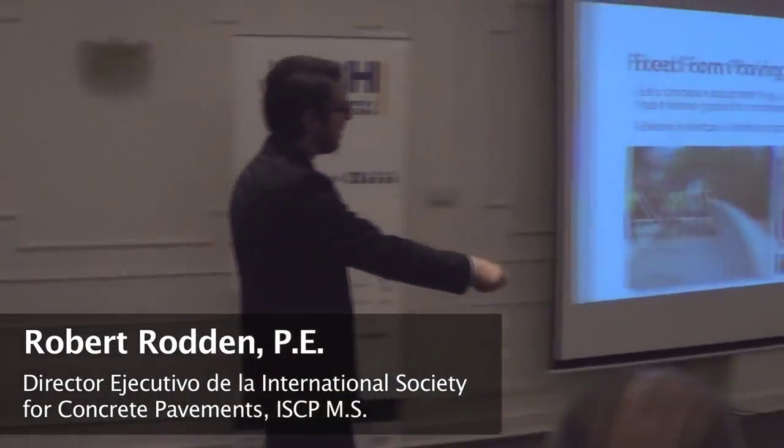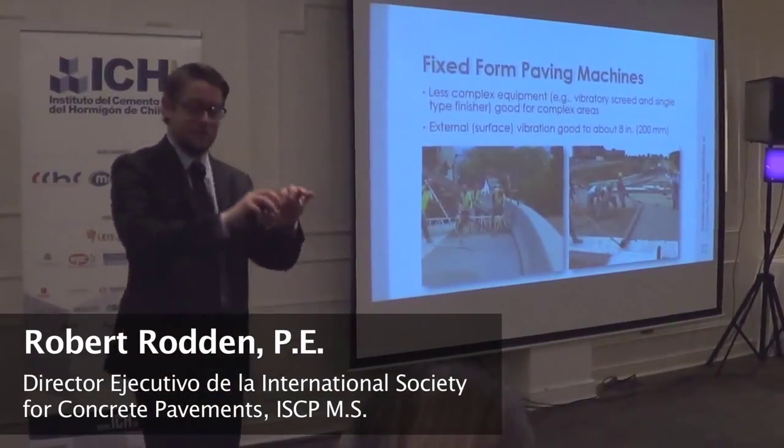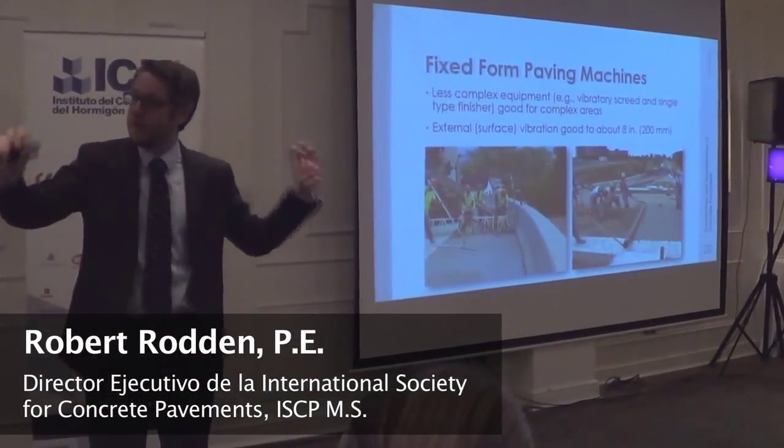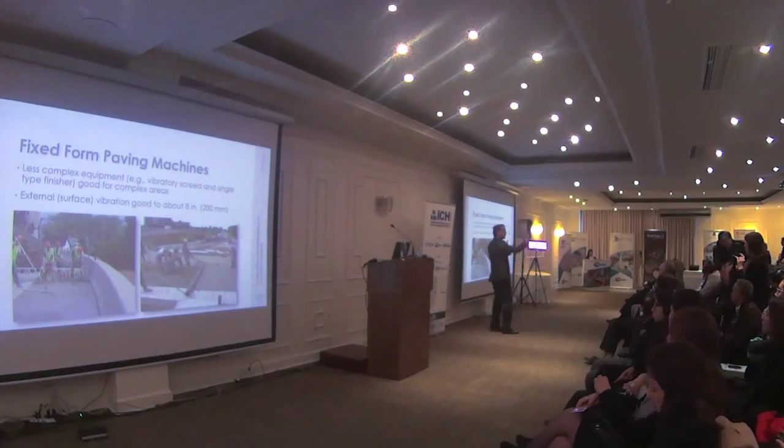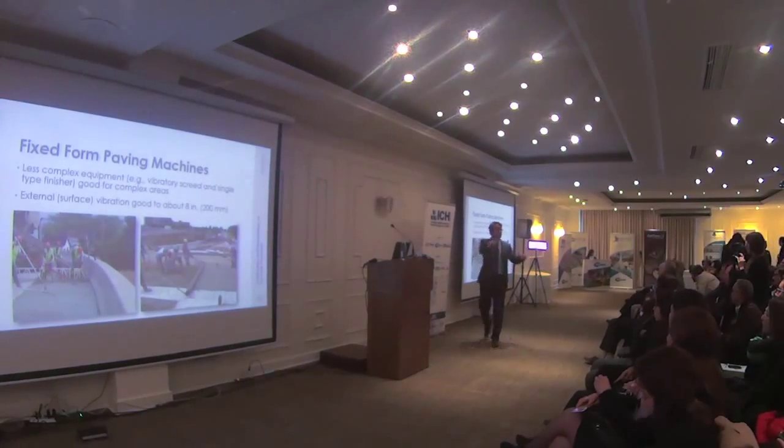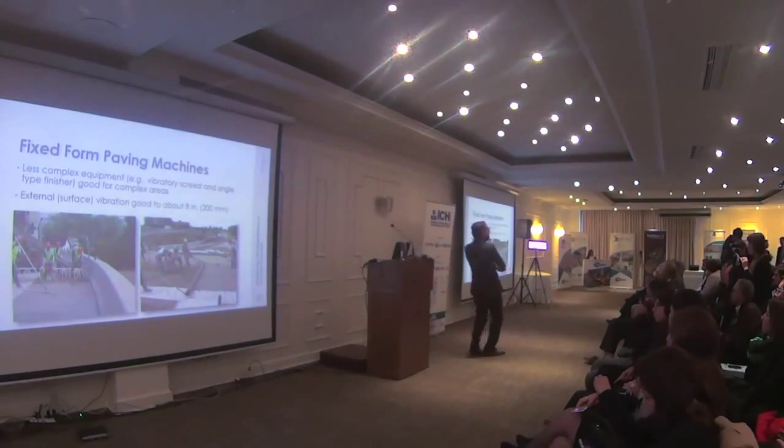The single tube screed, just a cylinder of steel, bring it out into the field. We fill it with water to give it some weight, so it pushes down on the concrete. And this gentleman in the background has a little throttle. And when he pulls that throttle, there's a little engine that spins it away from him. So it's constantly spinning in the other direction, which is why they're fighting to pull it back. You'll see that in the photos.